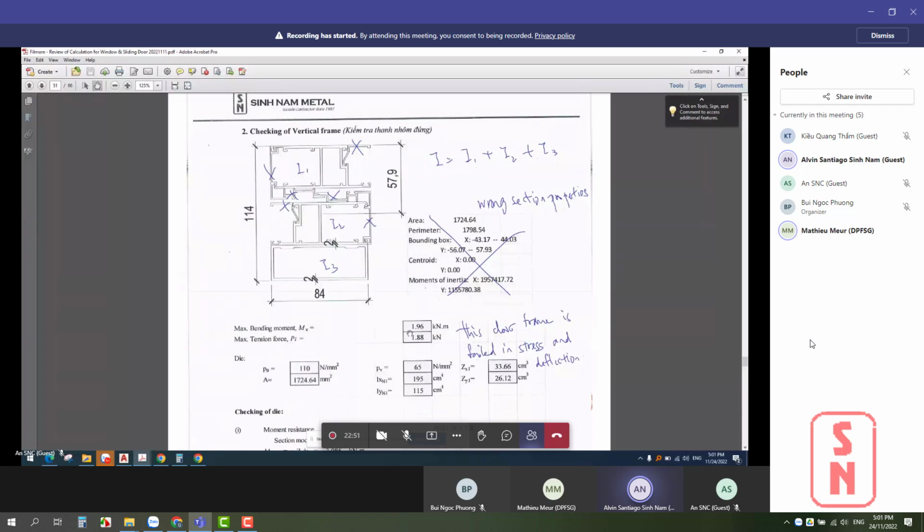But this one you have to be careful. That's what I meant by the sliding doors. You cannot do that, right? You know why, right? The top part is independent. The top part is not fixed to the bottom part. You know what I mean, right? Yes. Let's say the I2 and I3, the middle extrusion and the bottom box extrusion, you can fix them together by screws and consider it as one component, one monolithic element. But the top part is independent, yeah?